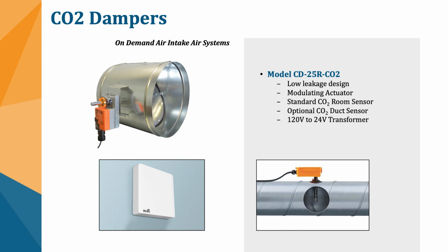And that's because the systems aren't as complex. You're not going to have bigger air handlers like you would on larger buildings where you're using, say, face and bypass dampers or other control dampers to recirculate that air or not. You might just be worried about opening and closing that, say, dedicated outside air system if you're dealing with apartments or things like that that are maybe separated through different occupancies, or don't have that common return and common exhaust, that you're in common intake that you're dealing with for a full building solution for your intake air. So these are going to be a little bit different.